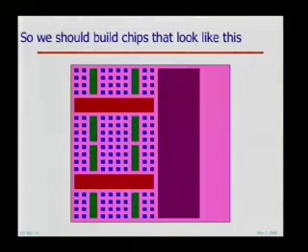So you have to introduce the intermediate level here, and then I've drawn another intermediate level, the red one here, where you basically stage into the green one from the red one, and the green one is big enough to tolerate the latency it takes to access things from the red staging of memory. And by the way, its size is driven by that latency and driven by working set considerations. Then the big purple one, and this chip would have several of these, but I got tired of drawing little squares at some point in time.